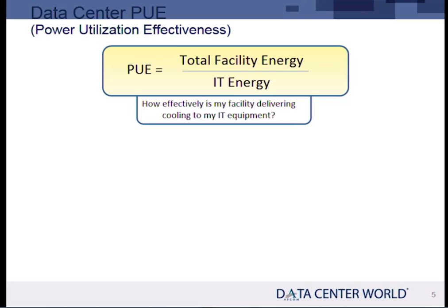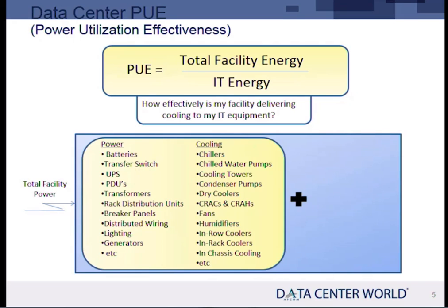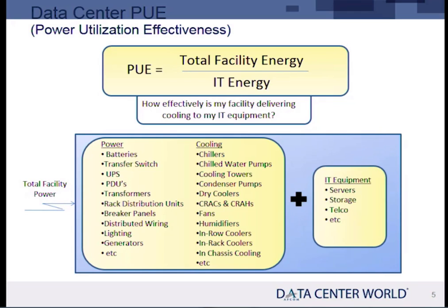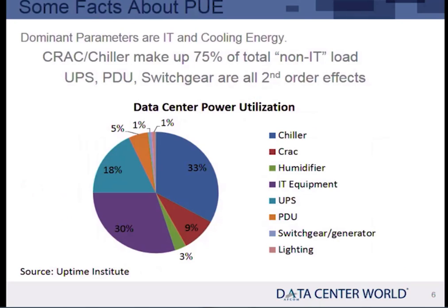So let's talk about first PUE. Most everybody here knows what it is. I'm just doing a level set here because I don't know where you all are with respect to understanding these things. PUE is a fairly good metric. It suffers from a few things. It is in the numerator total facility divided by IT energy. Total facility includes, of course, the IT equipment itself plus all the stuff extra to make that data center work. Okay, so that's the ratio.